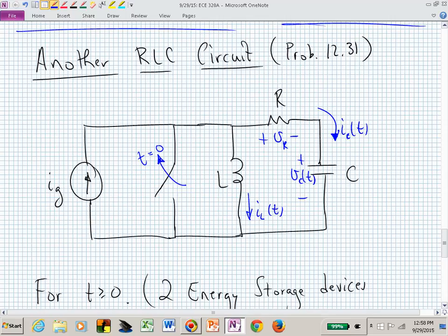What's one way that you could maybe approach this circuit analysis? How would you now try to find some equations that govern the behavior of that circuit? KCL is a good choice since we did KVL on the last one, and this one doesn't quite look like a one mesh problem, does it? What if we look at KCL at node A?